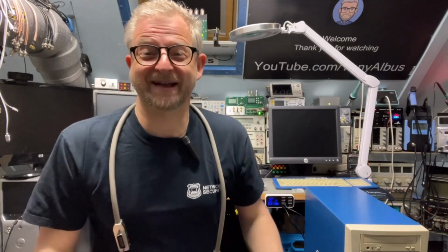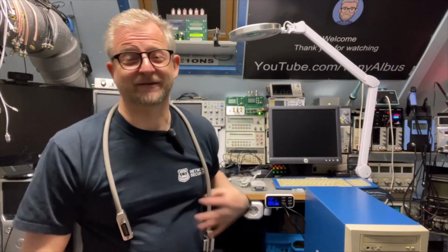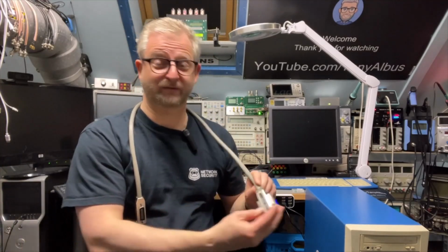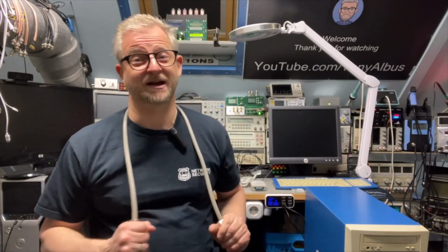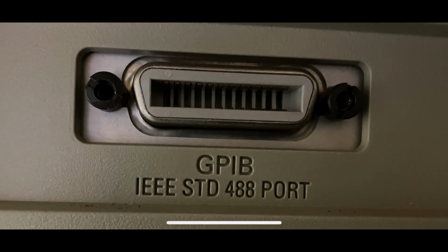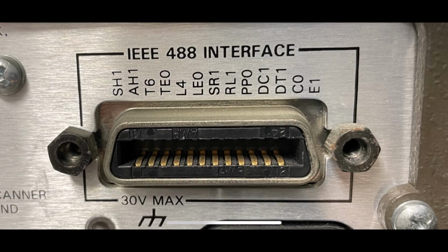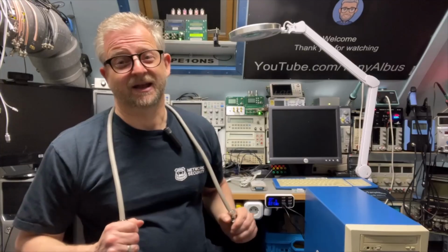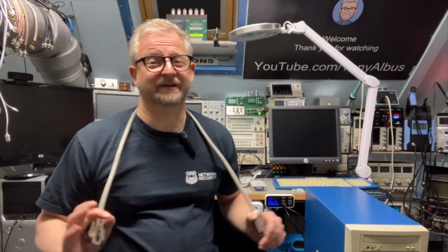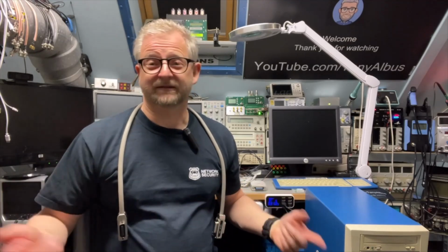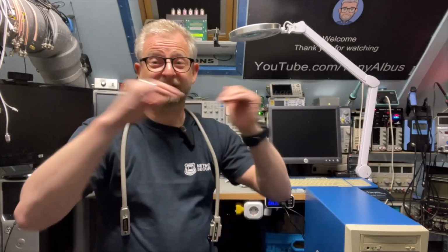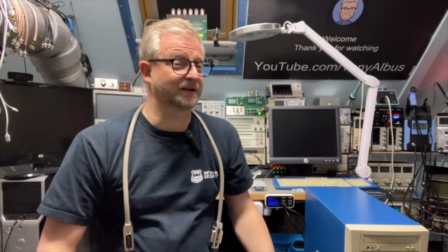Hello and welcome back. Today I want to play a little bit with GPIB or the IEEE 488, and in the past by HP it was even called HPIB. And that is a general purpose interface bus, and it is to communicate with your test equipment. And nowadays you just do it with your Windows 10. There is a VISA layer in between.